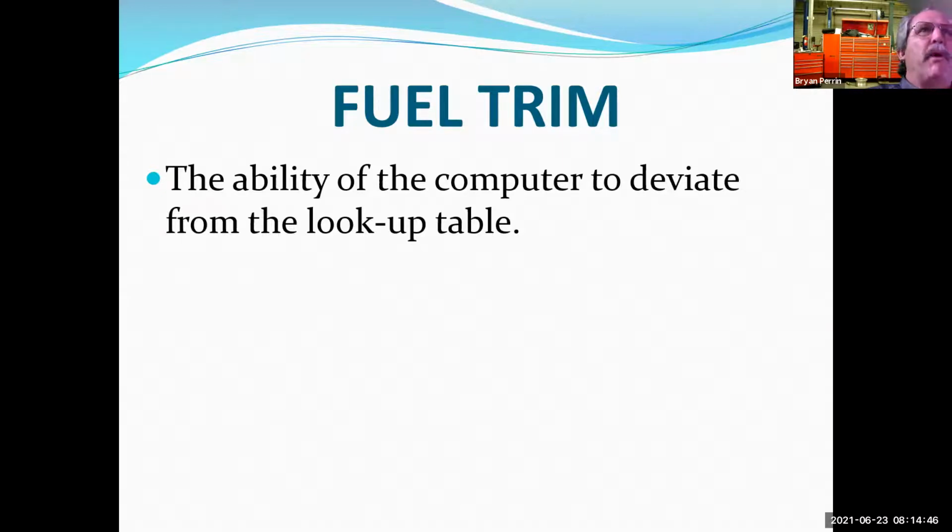But we know on speed density cars, a vacuum leak won't cause positive fuel trim. And we know that from testing I did in different videos. So if I have a Honda in and it's setting a fuel trim code at idle for running lean, and I've got good fuel pressure, I need to be able to go, wait a minute, why are we adding injector on time? Because obviously it can't be a vacuum leak because it's a speed density system. So now I have to really start racking my brain, what could cause it? Because speed density systems don't fail lean, they fail rich.